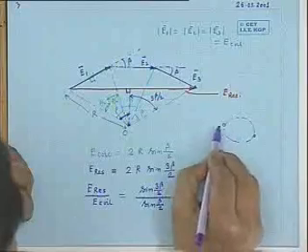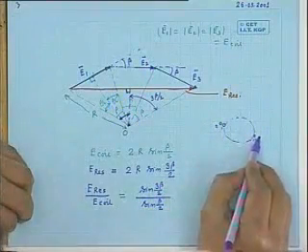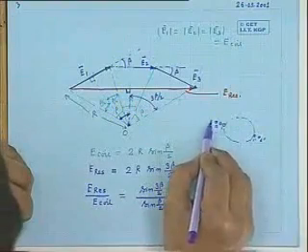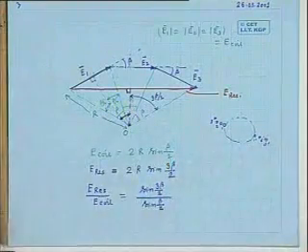But suppose all these 3 coils were concentrated in a pair of slots, then what would have been the induced voltage? And if these coils were connected in series, suppose in a non-distributed coil, this is coil 1, 1 dashed, 2 also you place here, 2 dashed, 3 dashed. That is, I have not distributed the coils. I could connect the 3 individual coils in the same pair of slots.